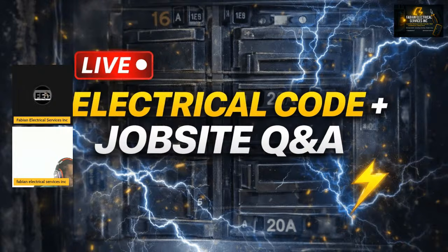Okay, so let's get started. Breakers protect the conductor, not devices. 15 amp versus 20 amp circuit. The 80% rule for continuous loads is out of the code book. Most people get this wrong. They size based on the device and not the wire. So I'm going to pull up the actual rule for that right now. I'm going to share the screen.